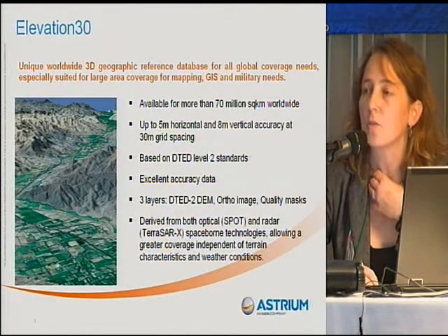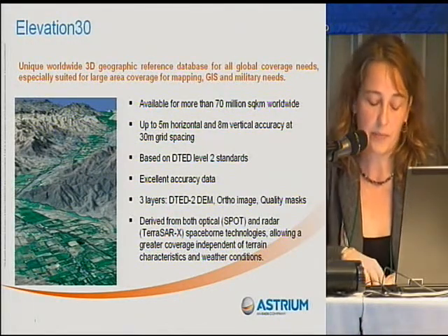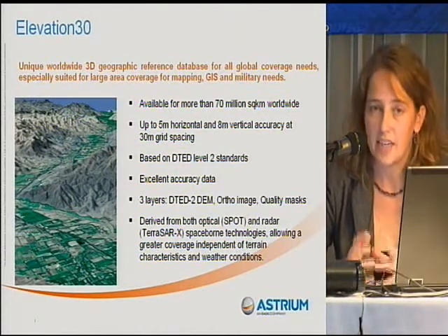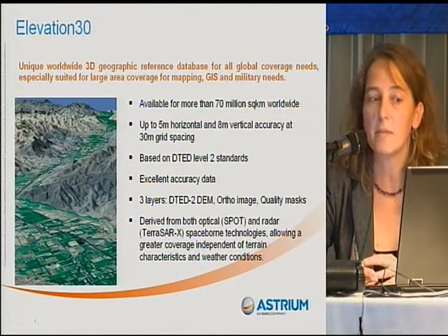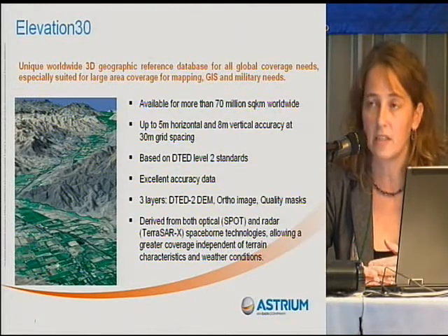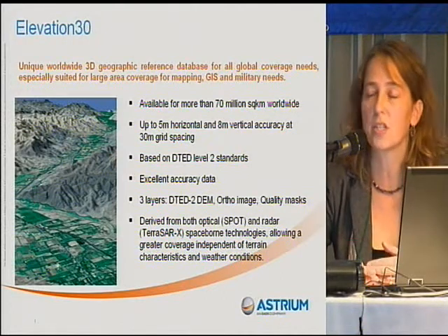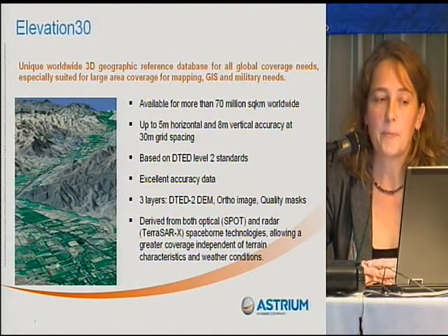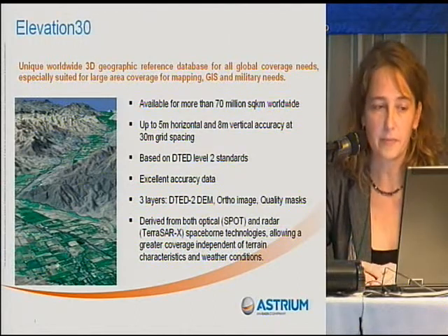Elevation 30 is based on SPOT 5 satellite data. The strategy is to build up a database. So in the meantime, we already have more than 70 million square kilometers worldwide in our database. The vertical accuracy goes down to 8 meter, and the horizontal accuracy can be up to 5 meter.